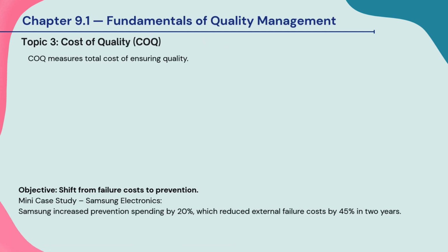This slide highlights ways to continuously improve capacity: reducing setup time using SMED, improving availability through preventive maintenance, increasing flexibility with cross-training, and using data-driven dashboards. The Tata Motors case shows how OEE monitoring and Kaizen improved efficiency from 78% to 88% without extra capital.